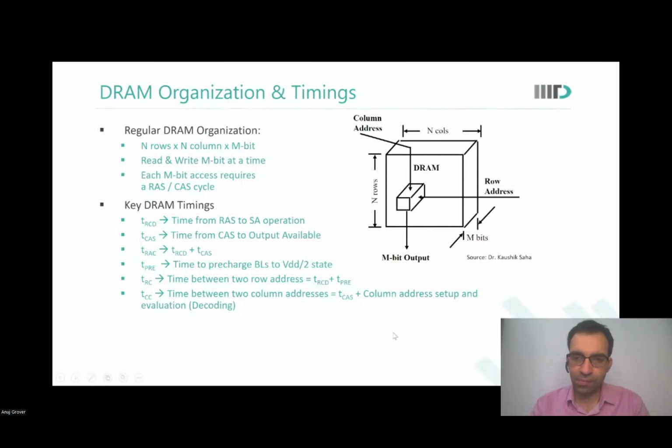Okay. Could there be a simpler way? Previously, we have seen the Q point stabilization thing in the SRAM. We can use the same structure over here to maintain it at VDD by 2. So can we put a resistance which will give an equal resistance at the bitline, so it will act as a voltage divider and give VDD by 2? What about power consumption at that time? Yeah, power consumption will increase because of that resistance. Won't work, na? Yes, sir.